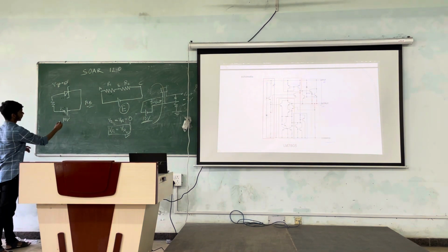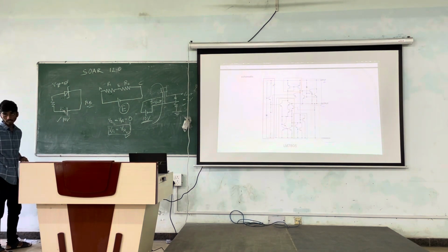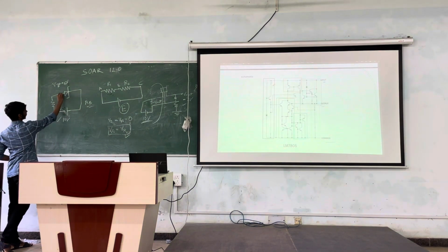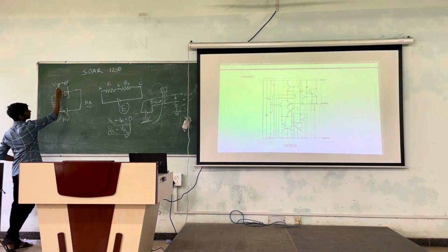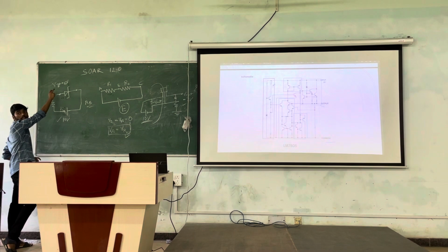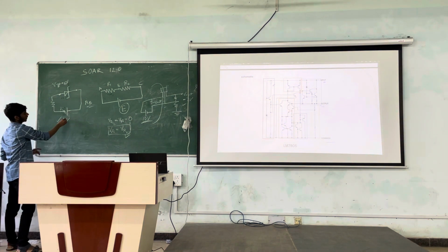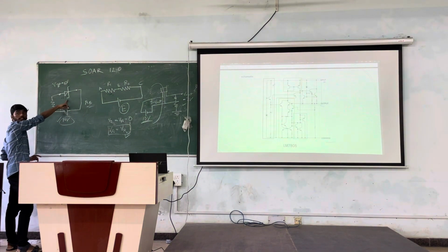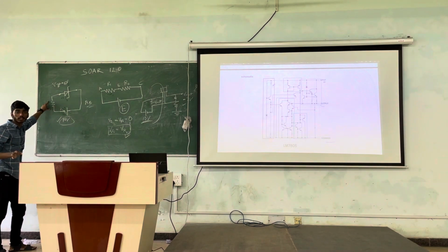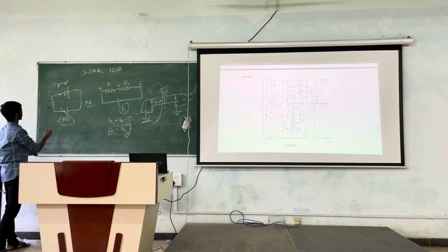And if we use this 10 volt supply here, the Zener will maintain 6 volts across its terminals according to its Zener characteristic voltage. What about the remaining voltage? 10 volts is applied here, 6 volts is dropping across this Zener diode. So voltage will drop across this resistor also, and that is 4 volts.